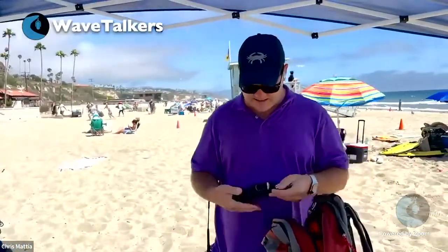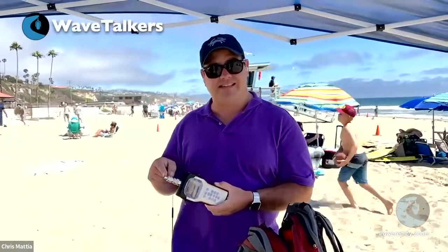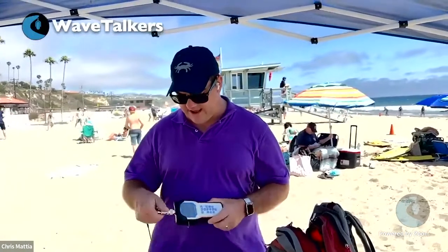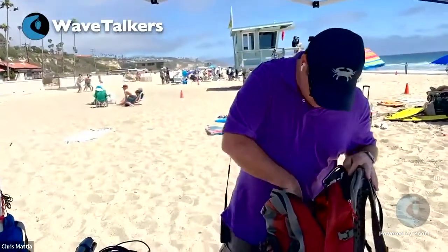In case you need it, you might want to have an antenna analyzer. I do have the Rig Expert AA230, and this comes with an N connector on it. What I do is I keep enough connectors to get all the way out to the BNC, which is what many of my radios use, so I can attach it to the different lengths of coax that I have. But it also gives me extra little connectors here in case I need to make an adjustment. So an antenna analyzer is super helpful to have.